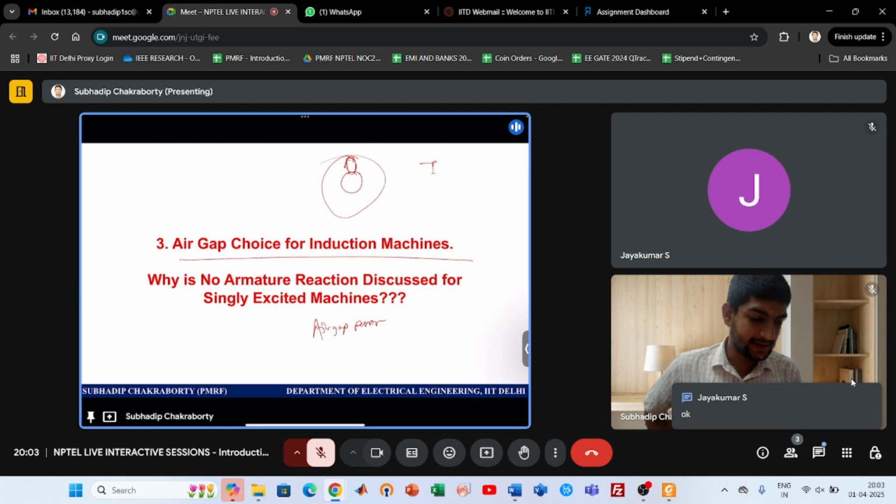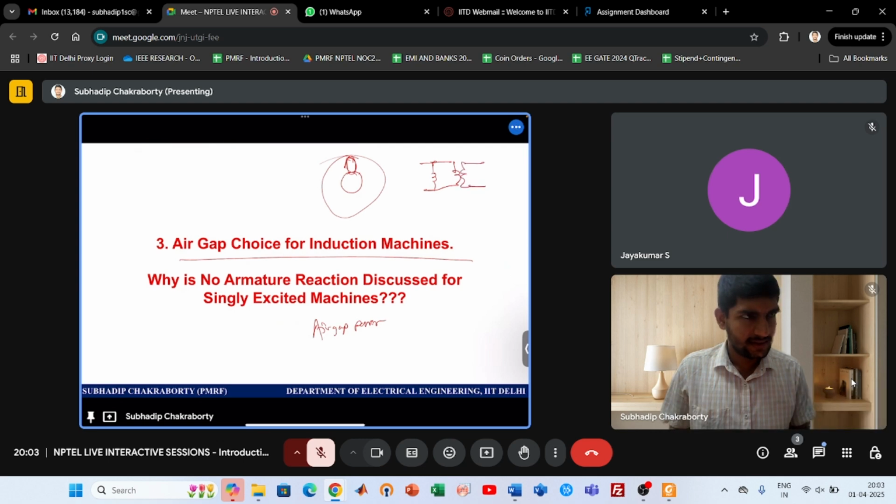You have the shunt path, right? I am modeling it as a simple inductance. And then you have the ideal conversion here. So till you have I2 equal to 0, there was only I0. That was very small in amount, because it was completely iron, right? The no load current, I am telling, very small.